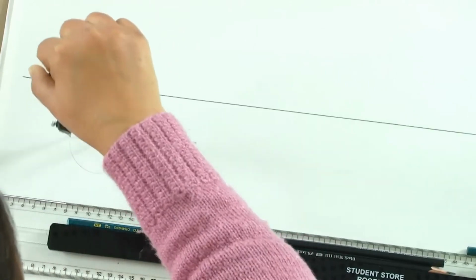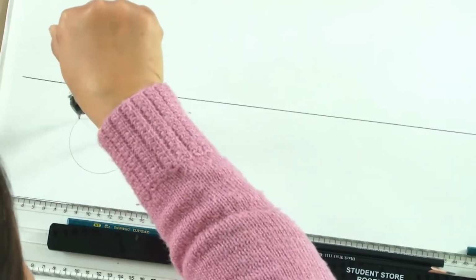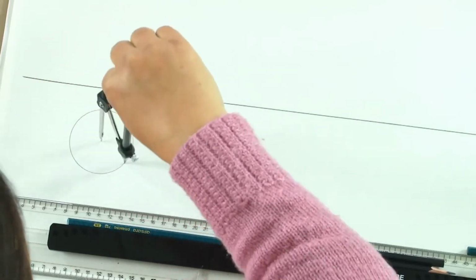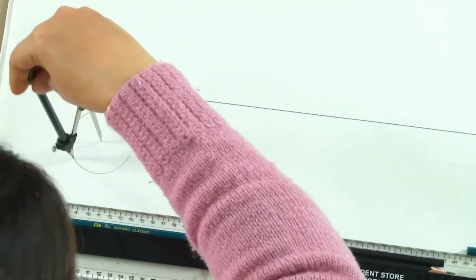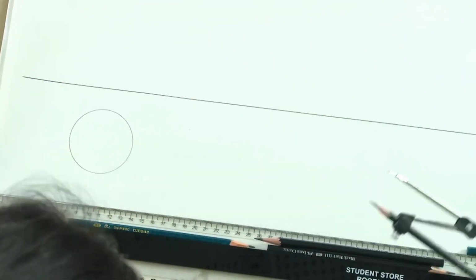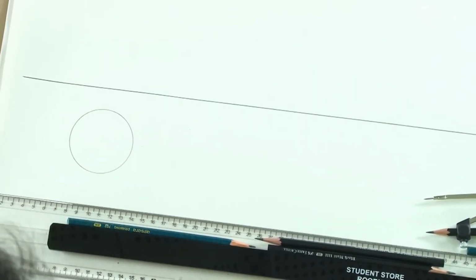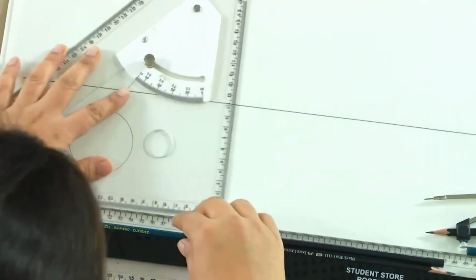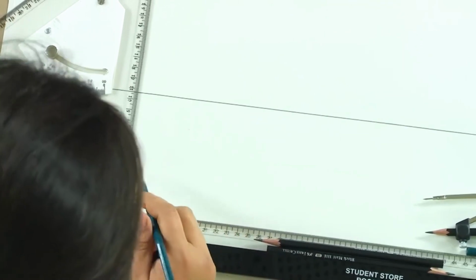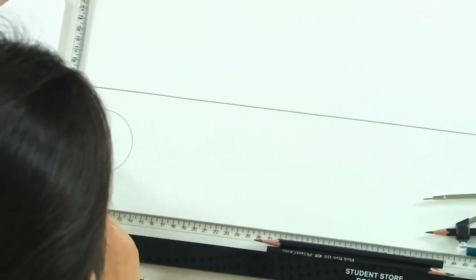the original, in case assuming that the circle was parallel to HP and perpendicular to VP. So we will draw its projections. Now this that we are drawing, which is the initial position which we have assumed, we will draw lighter. It will not be drawn very dark. Then we take its projections.